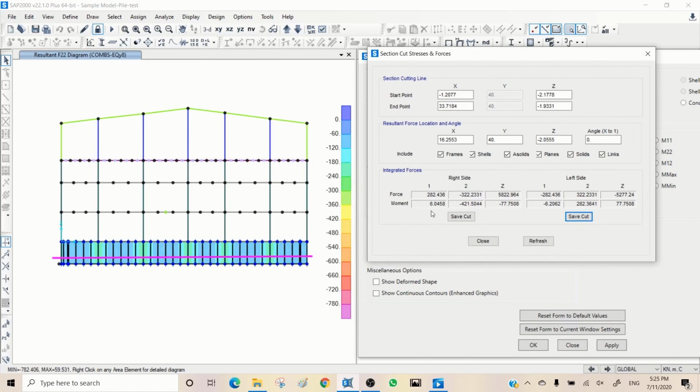So currently these numbers are here. You can see the total Z, for example, axial load is 5,822 kilonewton. So if I play with this, for example, currently it's all the way. So I want to, for example, make it just very small. I can check the coordinates, or I can play with these numbers to figure it out. So it's from -1 to 33.